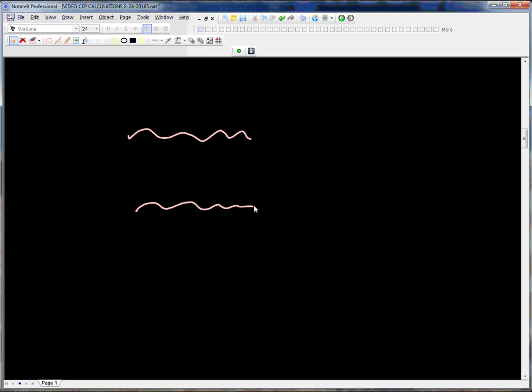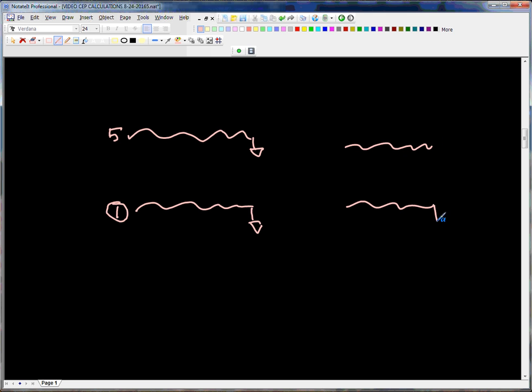But let's take this one and we'll ground it here. We'll put 1 volt here, put a circle around it, and we'll put 5 volts here. This is how we start. Normally we actually start with a winding where we had two layers like that, and we would probably say we had 500 volts here. That's 5 times, so this would be 2,500 volts up here.